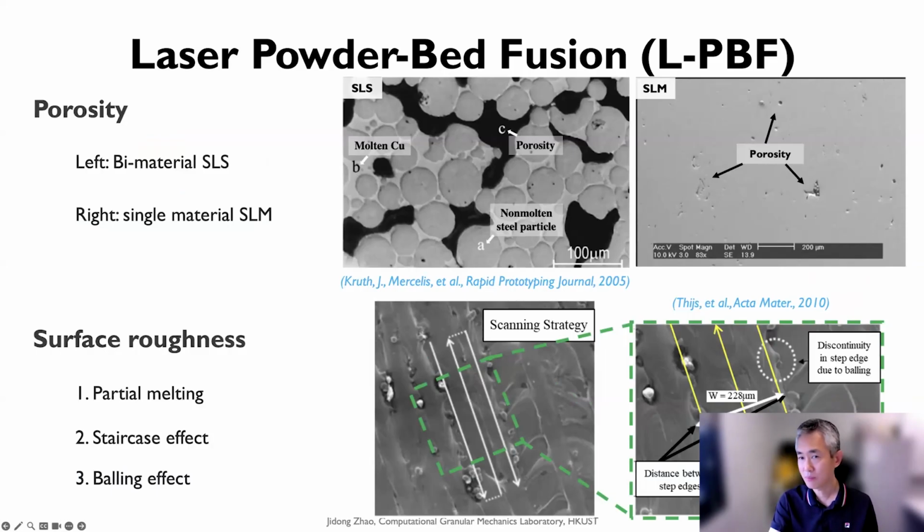And even the selective laser melting technology can generally help us generate high strength metals and alloys, but essentially a big part can also leave some porosity. This porosity can be quite a major defect that affects the performance and even failure of the part here.